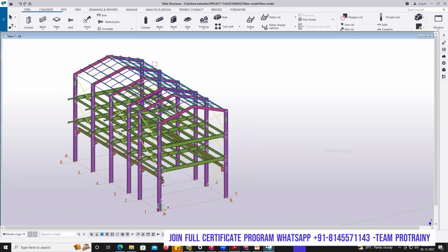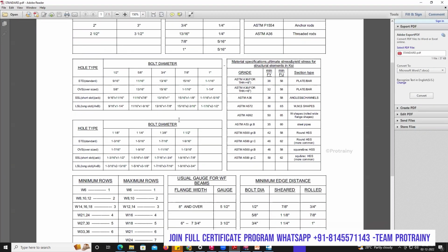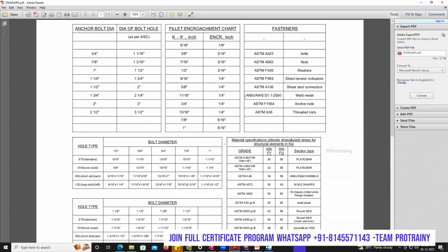As I represent here, you have to know the standard usage of the materials you are working with, what metal you are using and what the grade is, the bolt size you are giving, washer detail, nut detail, and the weld detail you are giving on 2D drawings for attaching the two components, whether it's necessary or not. Based on the thickness of the flange and the thickness of the gusset, the weld sizes will differ. Those are more technical details you have to get into a clean set of knowledge. Based on that only, you can work on this.